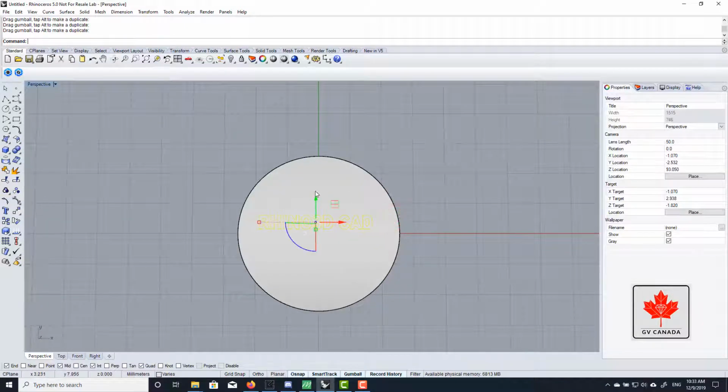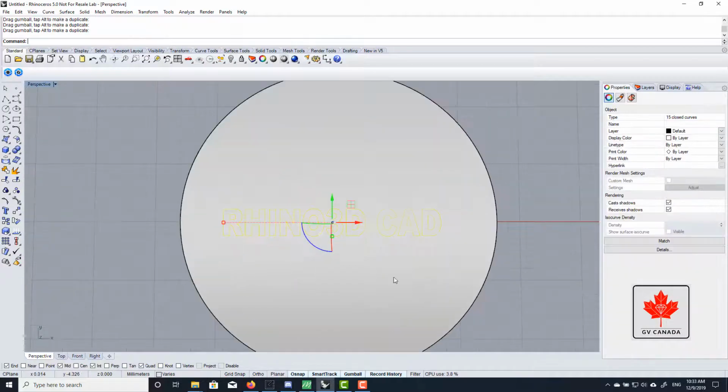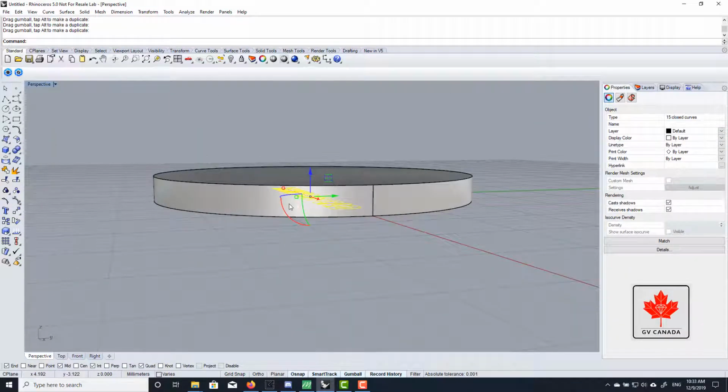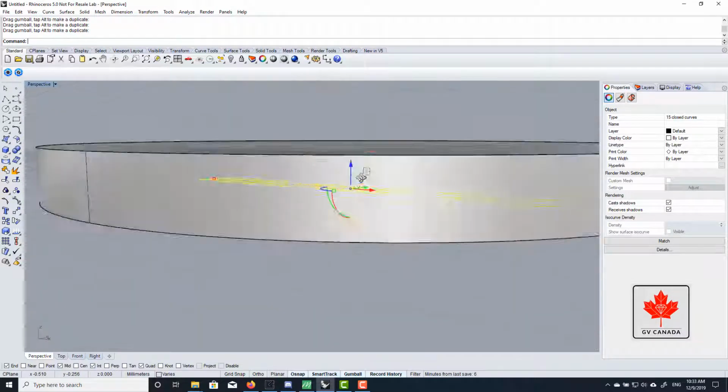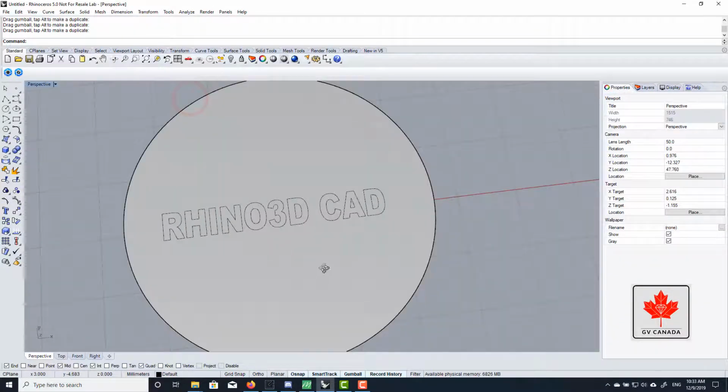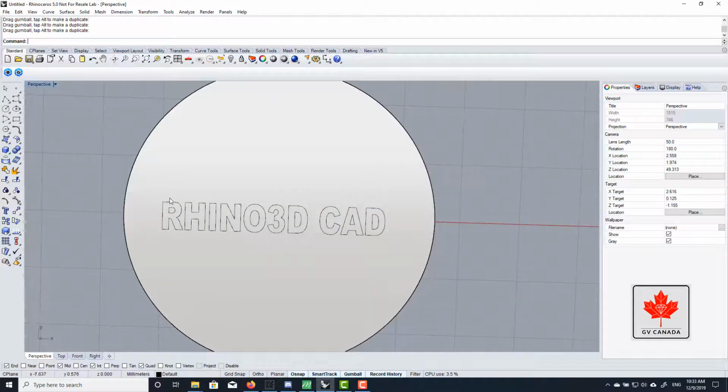And then I'm going to position it on top of my circle pendant. Okay, so I know this is 2 millimeters thick. So I'm actually going to click on this arrow here and type 2. And it's going to bring it up 2 millimeters, so it's lying flush on the surface here.